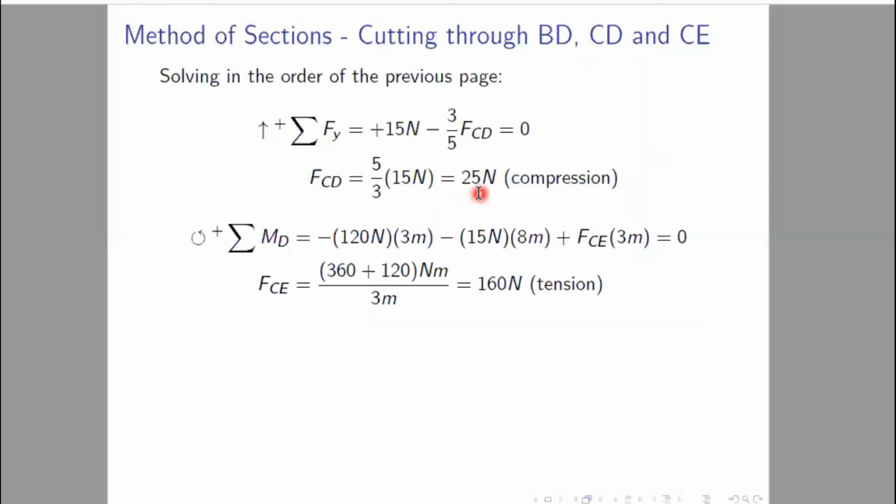And if we take the compressive sign convention, if the value comes out to be negative, you need not worry. It actually indicates that the member force is tensile in nature. So your problem is not wrong. While mentioning compressive or tensile force, you have to mention that.